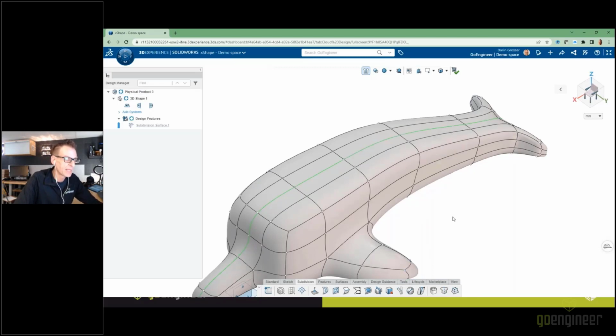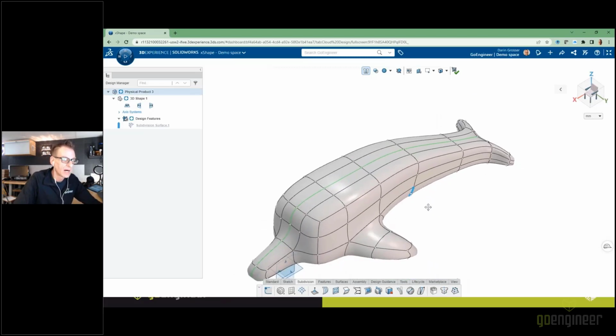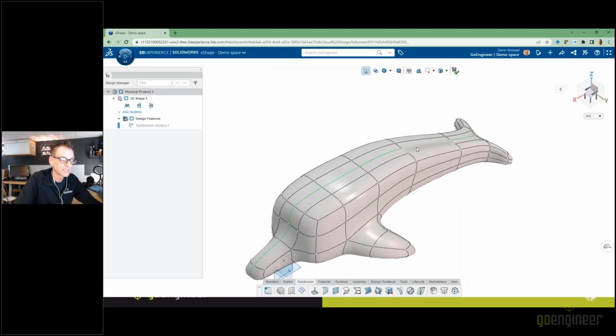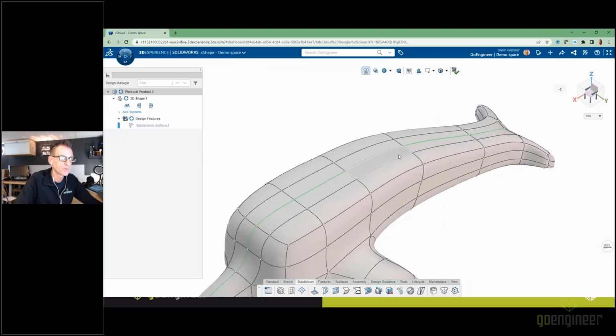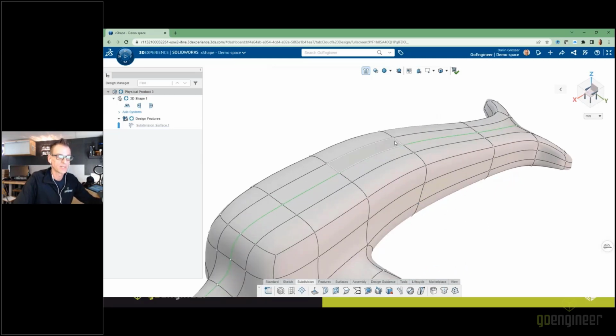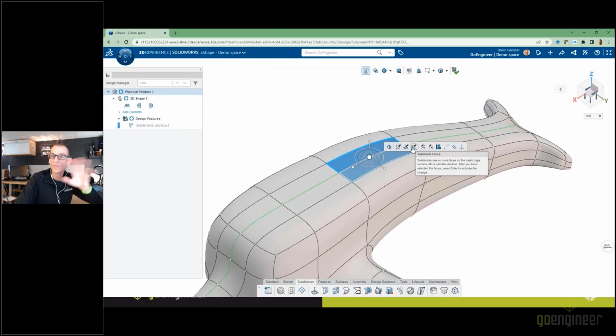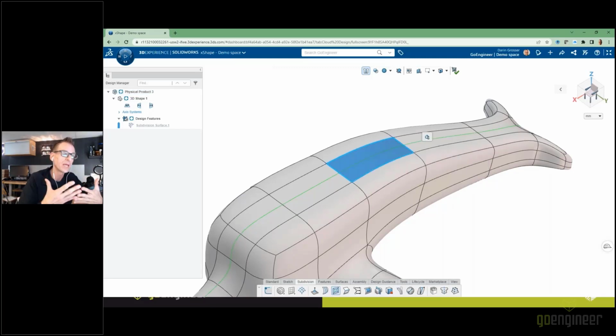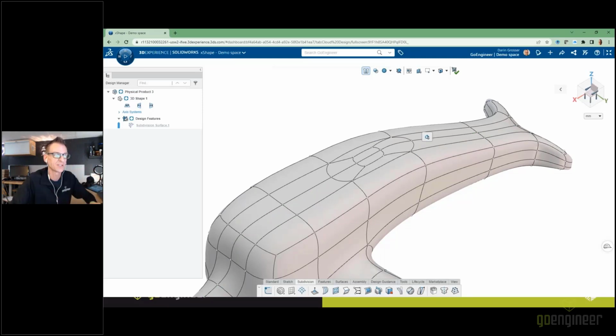Now, the symmetry being off doesn't necessarily mean that this part doesn't stay symmetric. It just means that things aren't necessarily active as we're doing that. What I do need, though, is another little region to work with. I'm going to do that by selecting a couple of faces and using an area called Subdivide. What this will do is give us 5 faces, one in the middle, and then adjacent faces so that we can control essentially how the adjacent transition or tangency is going to work.